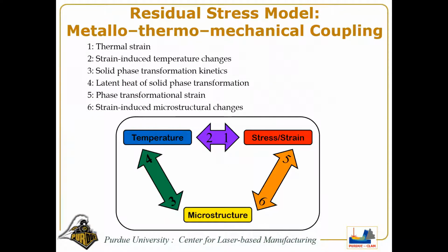Another part that we have been working on is predicting the residual stresses. So it's a thermally induced stress. And so you know that by the time you build the metal added parts, you don't see this much on the polymer parts because they are performed at the low temperature. And for metal parts, you'll get thermal stresses. So you can have a distortion or residual stresses left. So these things actually involve many different mechanisms.